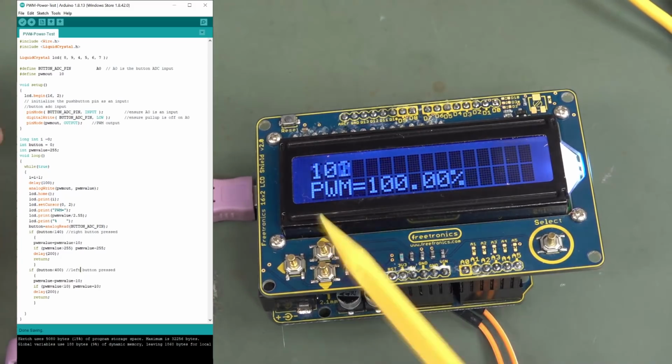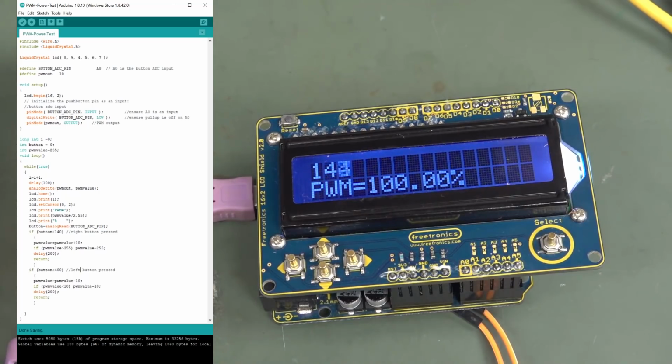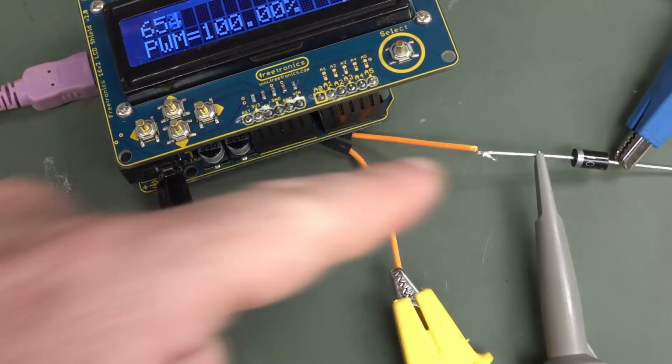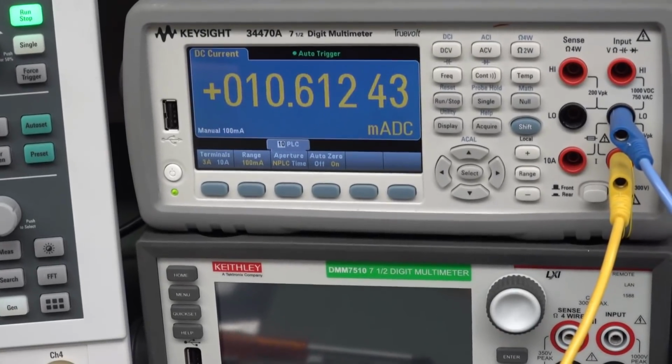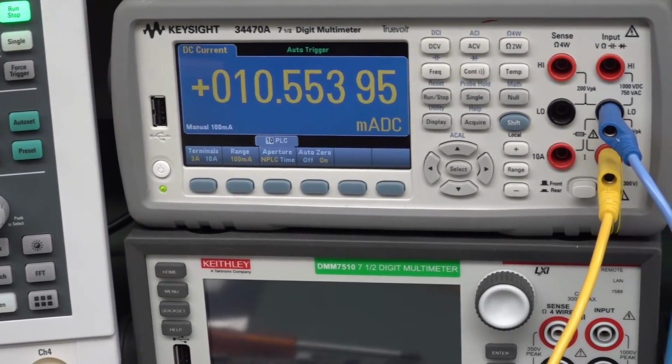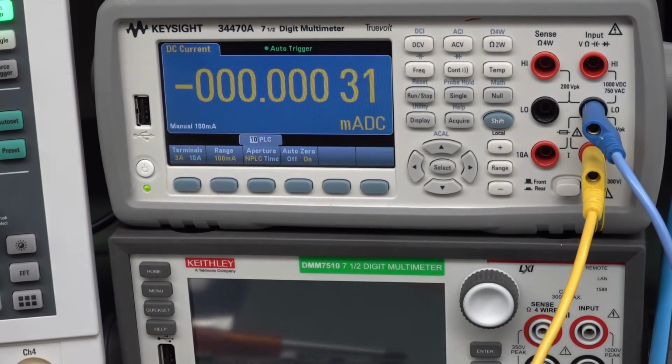It's just counting, it's just doing something. It doesn't mean anything. And I can actually set with the switches here the pulse width modulation value going to the pins. At the moment, it's 100%, so that chip is not switching. So the power is just permanently on. It's working like it normally is. And I'm also going to hook a scope across here. Okay, so at 100% PWM, it's just permanently on. We're getting about 10.5 milliamps there, which is about right for a 16 meg ATmega.